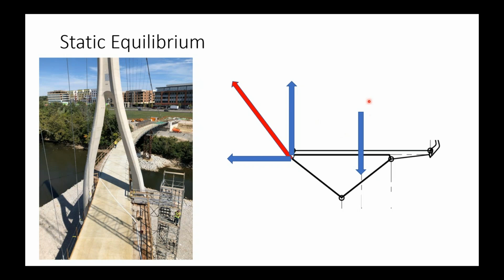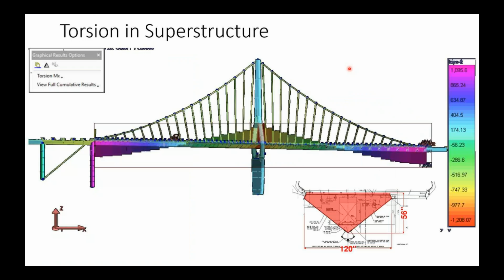And the vertical component of the load, of course, carries the dead load, but at an eccentricity, which generates a torsion. So the next thing we need to do is figure out how to handle this torsion and make sure that we are designing the bridge appropriately to carry this torsion in a stiff way that's not too flexible.